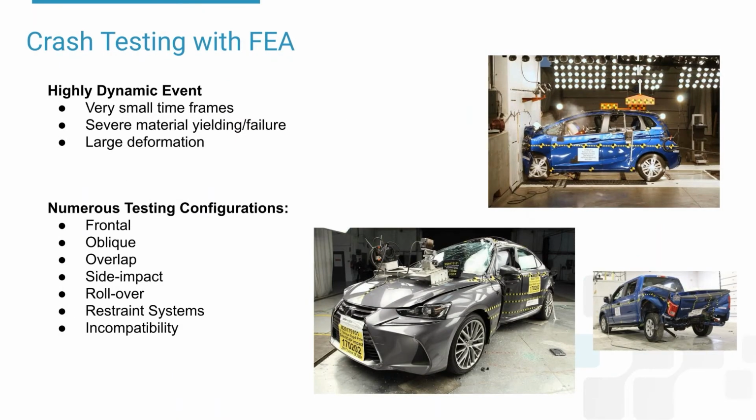The simulation that we'll be looking at is a crash test analysis. Crash testing, or really any kind of destructive testing, can be incredibly expensive to physically prototype, not just because of the cost and time of actually building these prototypes, obviously, but because the prototype itself can't be reused after the crash. So what a lot of engineers have done in the past, and are certainly doing today as well, is to move some of these workloads to FEA packages that provide solvers using mostly explicit methods to capture these very small timeframes that we're going to need to capture the impact, and also have the ability to simulate very nonlinear material models because of the severe damage and deformation that we get, in addition to the contact challenges that are present when we've got all these components under the hood in these cars.